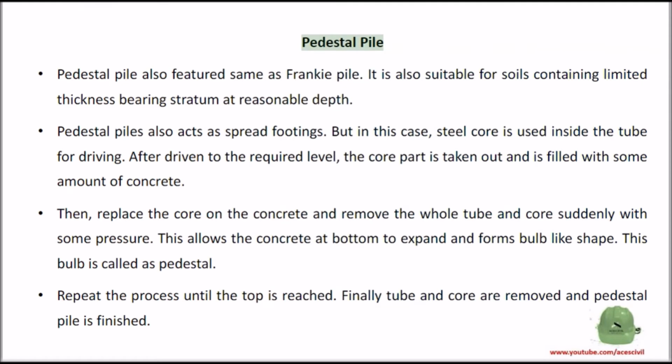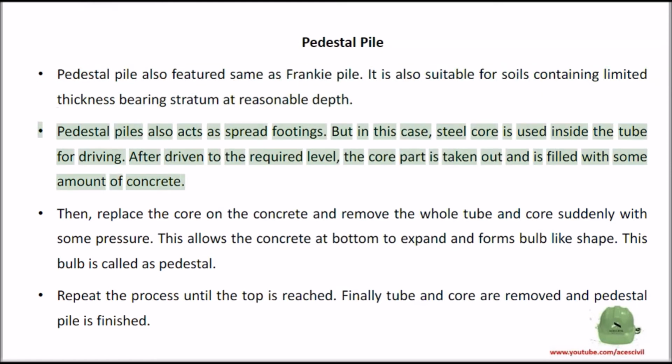Pedestal pile. Pedestal pile also has the same features as Franki pile. It is also suitable for soils containing a limited thickness bearing stratum at reasonable depth. Pedestal piles also act as spread footings. But in this case, a steel core is used inside the tube for driving.